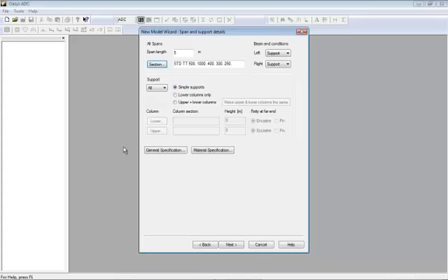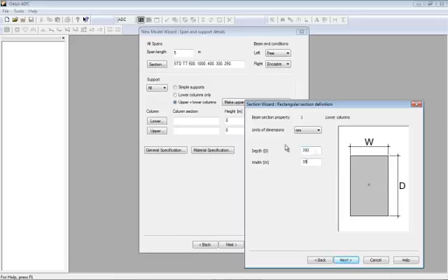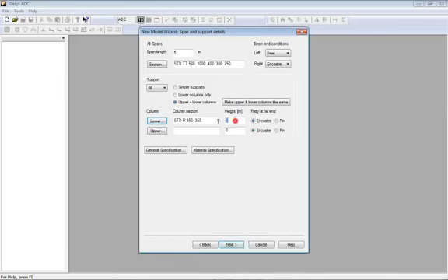We also need to set up some supports. So left hand support, I'll just make that free. The right hand support could be just a pin support, or we could encastre. Let's fix it in. Along the spans as well, we can have simple supports, or we can have columns above and below. So let's pick, let's say, a rectangular column, and this column will apply stiffness to the multi-span beams and affect the bending moments therein, and we'll just make the upper and lower the same size.